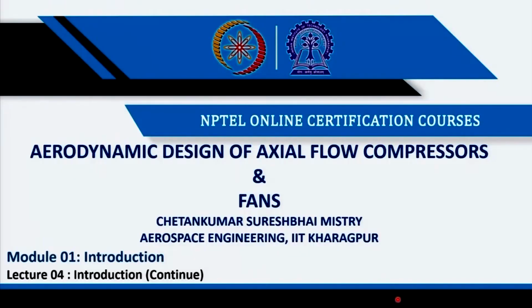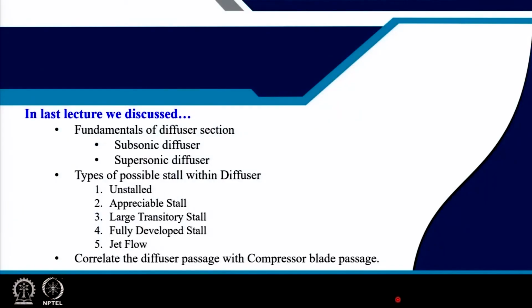Hello and welcome to lecture 4 for the course on aerodynamic design of compressors and fans. In last lecture we were discussing the fundamentals of the diffuser section, where we discussed the effect of area change with the effect of your inlet Mach number. And if we realize here, that has given us the concept of subsonic diffuser and supersonic diffuser.